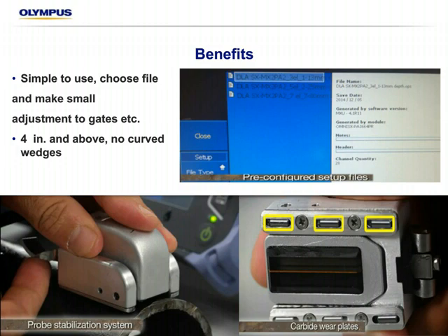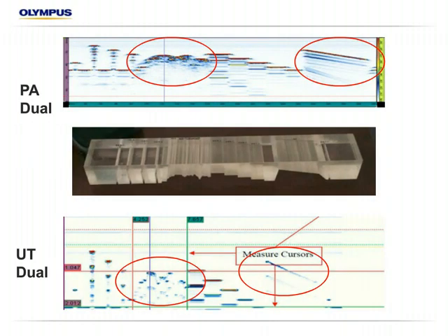So here are a few acoustic performance examples. This is a Rexolite block, or Lucite, plastic anyway. But it's a very good representation because it has all the types of targets we typically want to be able to detect when we're measuring corrosion. Here we have some flat milled steps. We have some simulated corrosion that was laser etched based on looking at actual corrosion profiles. We have the normal step wedge that a lot of us doing thickness readings would be familiar with. We have a slope of varying angle, and then we have a small notch in there as well.